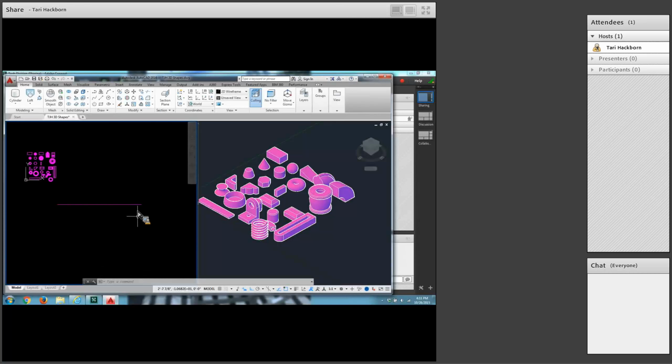Remember, you need the foot sign. If AutoCAD doesn't let you roll the mouse back far enough, draw the line first, type 2 feet and enter, then you'll be able to zoom out. Okay. Now looking at the dimensions on the bottom of the page, there is a dimension of 5.5 inches on the right side and 2 dimensions on the left side: 1.5 inches and 3. So that would add up to 4.5 inches, and when you subtract that from 5.5 inches, it equals 1 inch. So the first thing I'm going to do is come down 1 inch.